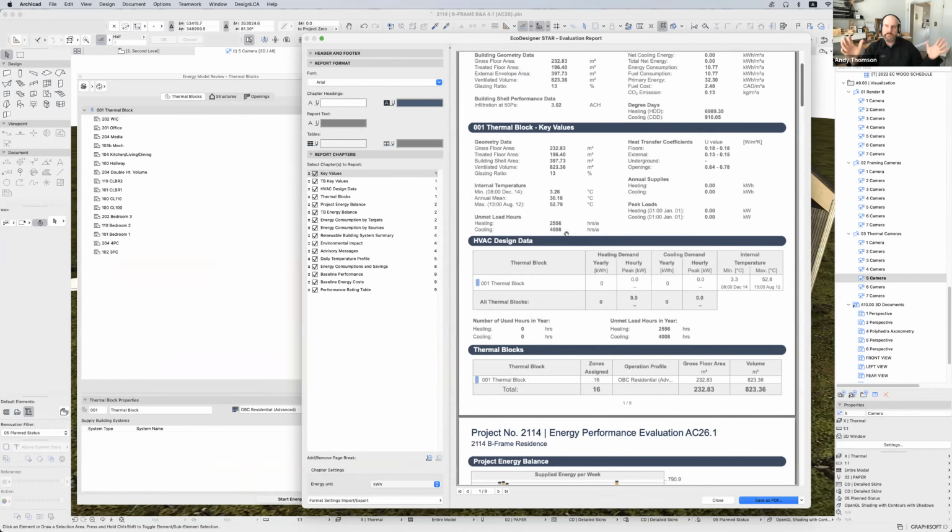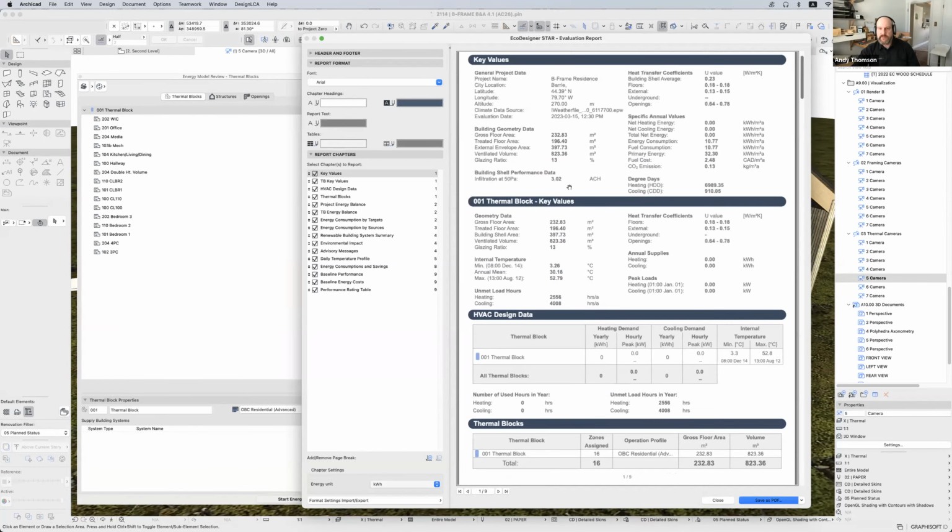So this is a really good building from a heating point of view, but not a really good building from a cooling point of view, which is what you start to find when you're doing high performance building design. Cooling becomes one of the critical issues, not so much providing heat for the winter. We can solve that easily. Just make a nice thermos that's not losing energy. But how can I make the heating even better?